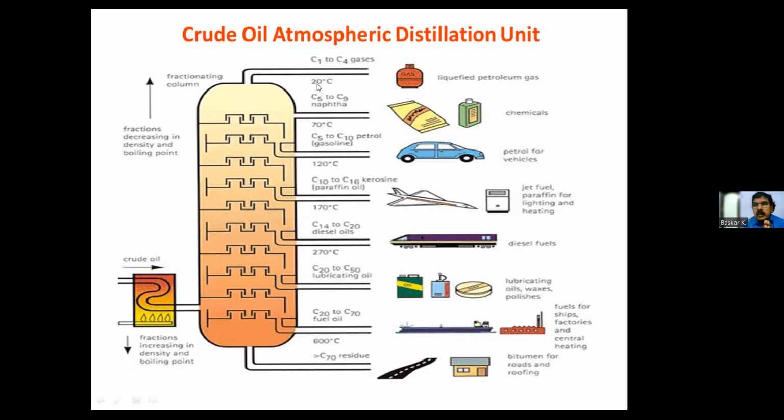How do we maintain it? We are using a system called reflux and pump-arounds. We are not using any temperature rods or temperature elements for maintaining different temperatures. We are using the same liquid as either reflux or pump-around. And sometimes we are also using steam as a pump-around for heating, for maintaining these temperatures. So I think I'll recap quickly.